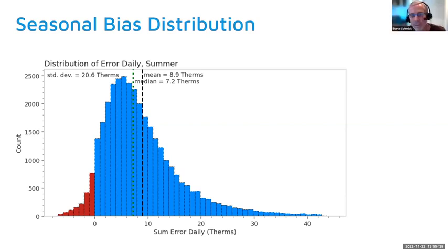Yeah, this is Steve again. I think we've seen this for all the homes we've analyzed, and we see that getting the balance point temperature correct is very, very difficult for many, many homes, and it changes throughout the year. So those two things are critical. So I would say that improving the method used to select the balance point temperature in CalTrack is a key goal. Thanks, Steve. Totally agree.